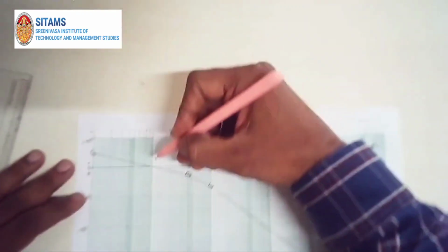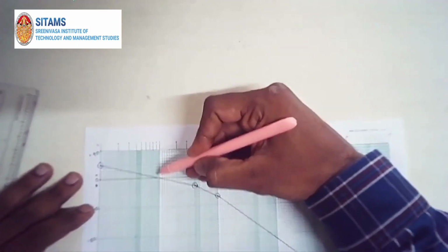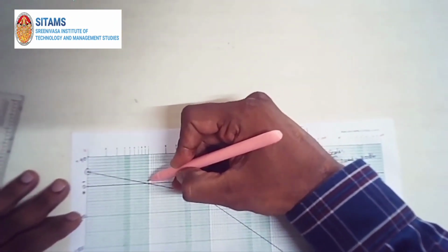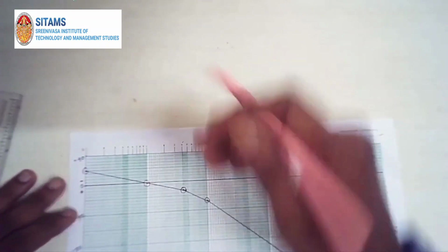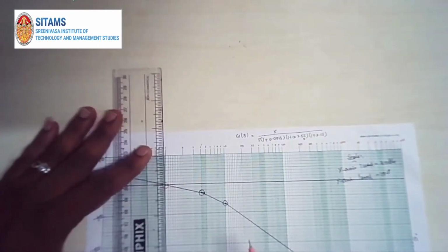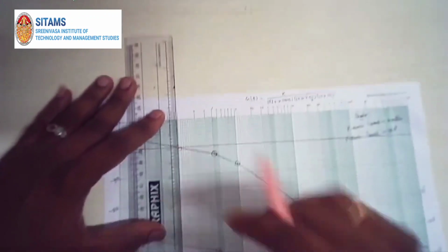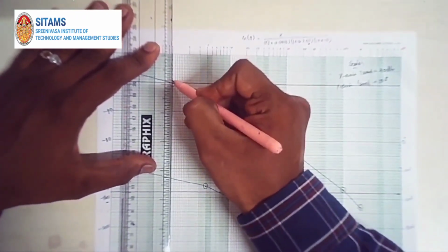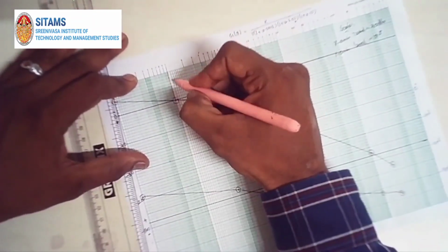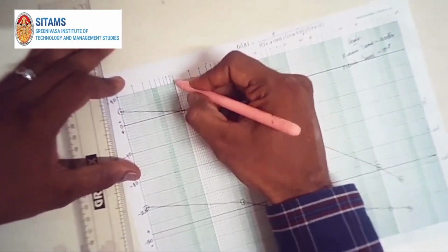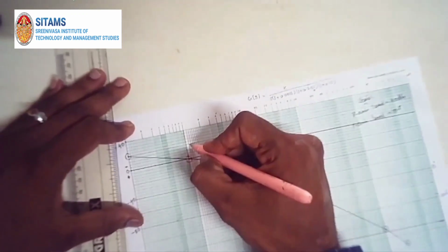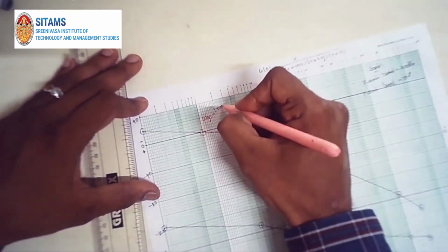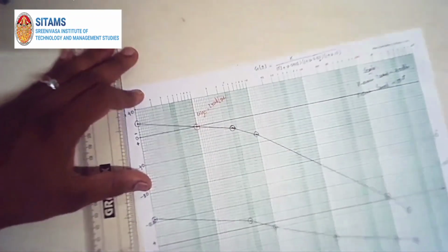So in this plot, if you observe the magnitude plot at this particular point, it cuts the 0 dB line. So you have to sketch a straight line along this intersection point and you just calculate the gain crossover frequency. So it cuts the line along 1 radian per second. So my gain crossover frequency omega GC is 1 radian per second for this problem.